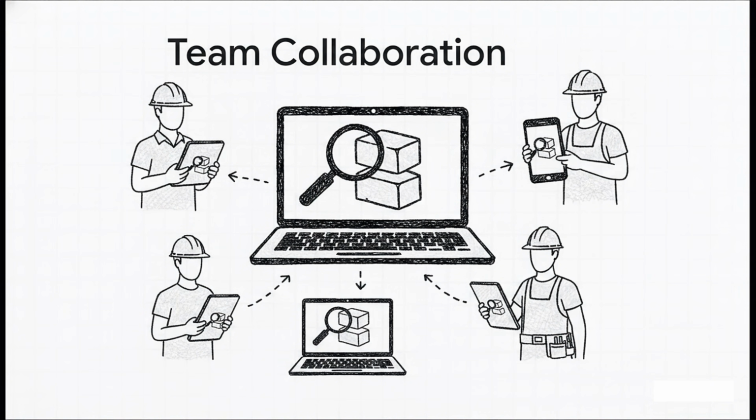The source highlights a phenomenal example. Imagine a framer sends you their model. Instead of you manually hunting for all their specific infills, king studs, and kickers, you just ask them to send their search sets along with the model. You import them, and wow, you are instantly ready to run clash detection the exact same way they do. It saves hours of manual data entry and standardizes the whole project across your project.